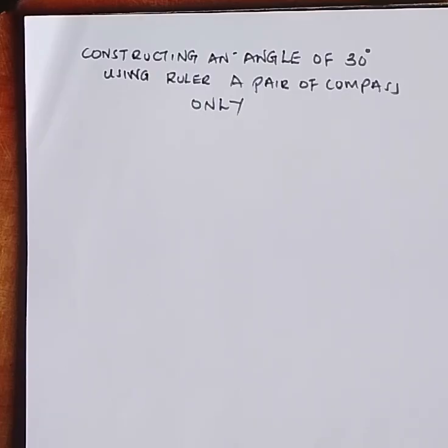In this question, you cannot construct an angle of 30 directly, but remember on the previous section, we saw how to construct an angle of 60 degrees. As you can see, 30 is a half of 60, meaning that if we can construct an angle of 60, then bisect it, we can get an angle of 30.